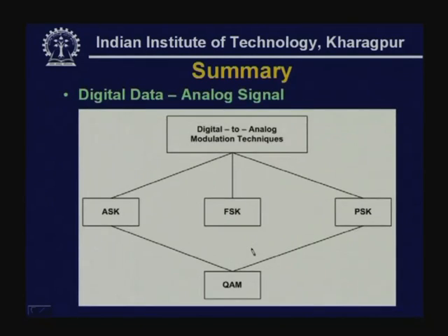Then coming to the digital data, digital to analog signal, we have discussed ASK, FSK, PSK and also QAM, and we have found that ASK is simple, and particularly the on-off keying is very attractive, which has found application in optical communication, where the optical signal is modulated by using this on-off keying, and the bandwidth requirement is less.